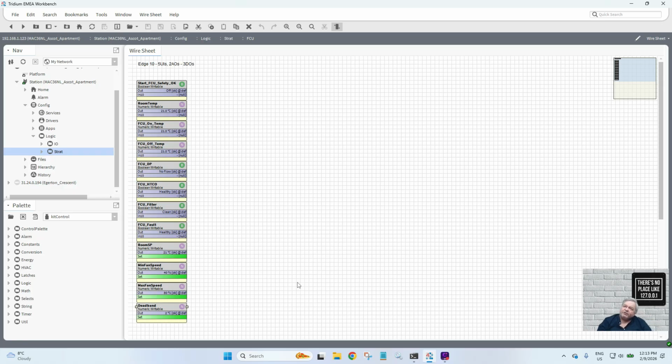Do we want fabric protection? So that if the temperature of the room goes below 16 degrees, we actually put the fan coil on even if it's not being asked for. And then, do we actually put a PIR in the roof so that the fan coil will start when someone enters the room, rather than having an enable as well? So that would work, wouldn't it? So let's do the PIR business.